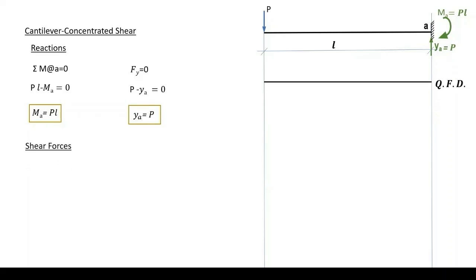Shear force diagram. Starting from the left-hand side, we will head downwards if the force is downwards, and we will head upwards if the force is upwards. And along the beam, the shear is accumulative, meaning we will add and subtract forces perpendicular to the beam, in the direction of the shear, as long as we meet them.